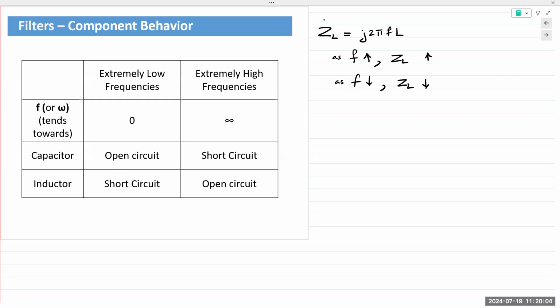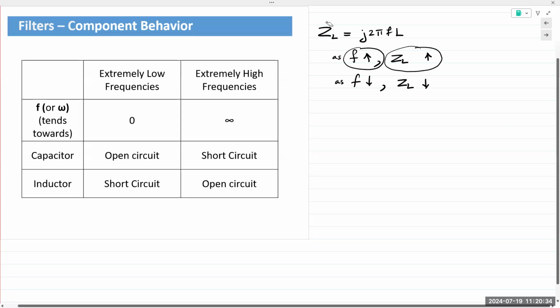So once the magnetic field is full, energy storage is full, inductor behaves like a short circuit until you start to change the input. When you change the input, inductor reactance will oppose any change in that input. And so the faster it changes, meaning as frequency increases, the faster it opposes any change in that input, which